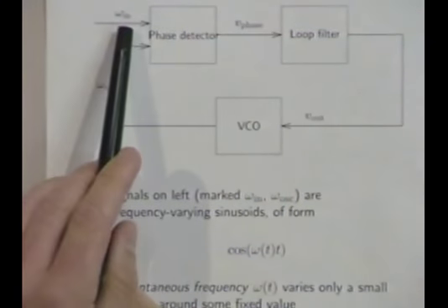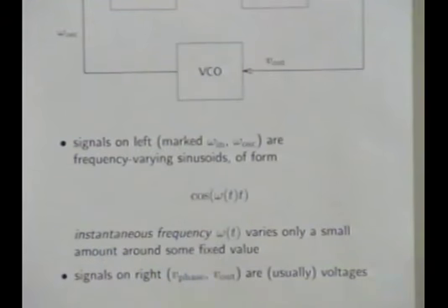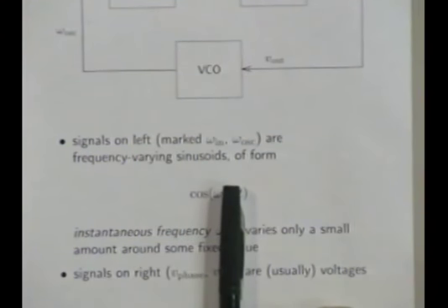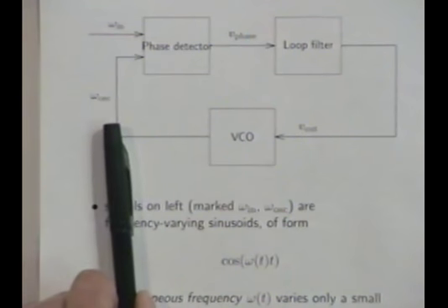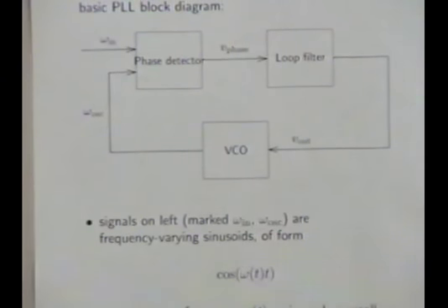And I really shouldn't say, casually we say this is a sinusoid. The truth is it's not a sinusoid. It looks like this. It would be a sinusoid if omega were constant. This is a sinusoid. So if there are mathematicians or lawyers present, you could not say that this signal is a sinusoid, because a sinusoid by definition has a constant frequency. But if there's just regular people around, you would say it's a sinusoid with varying frequency, right? It would be like saying, what's the signal coming out of an FM transmitter? And pretty much it's a sinusoid at 88.1 megahertz. And then if someone says, really? And you say, well, no, in truth, the frequency varies plus minus 15 kilohertz around that, which is in the fourth digit. So anyway, you get the idea.